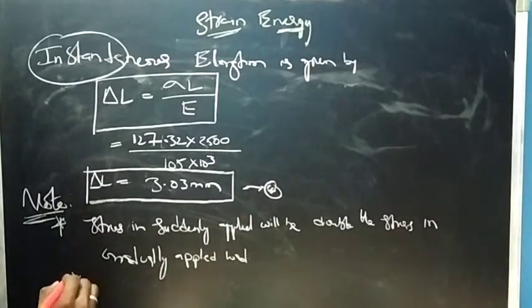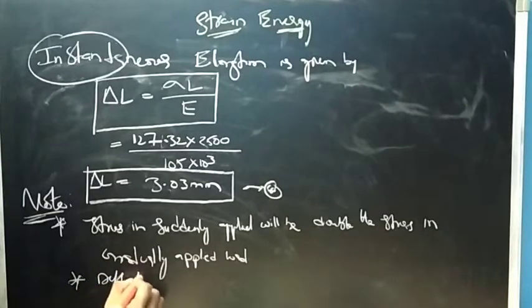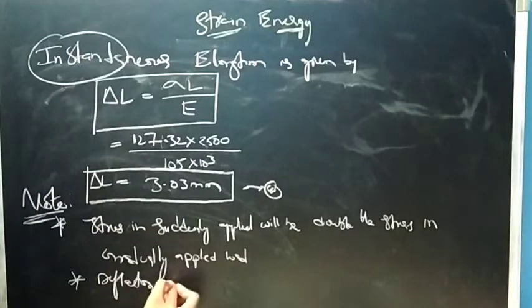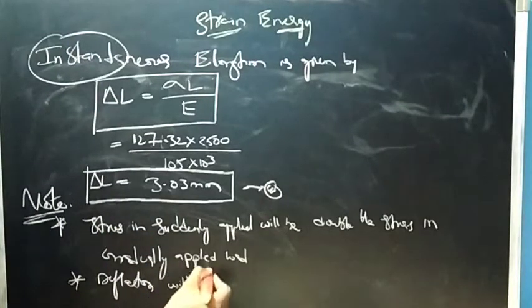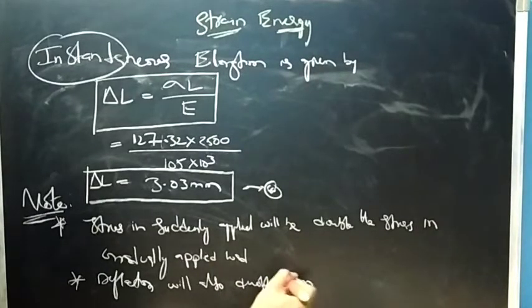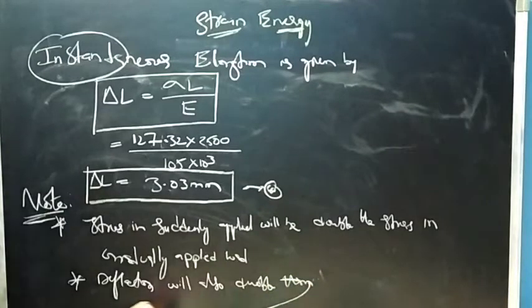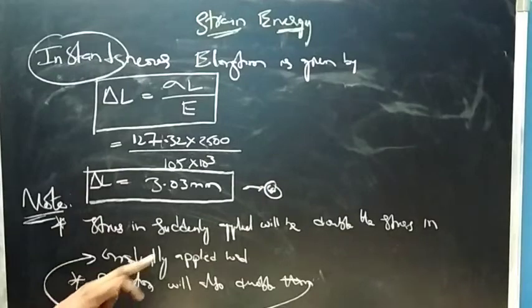As well as the stress being doubled, the deflection, or you can say the instantaneous elongation, will also double. This is a point you have to remember: double that of the gradually applied load.